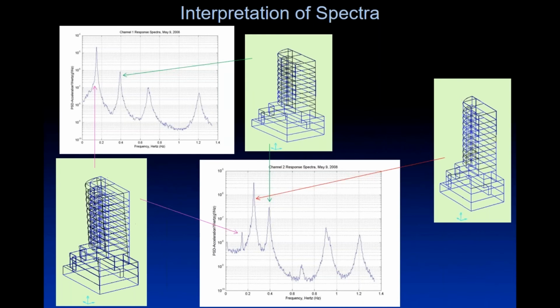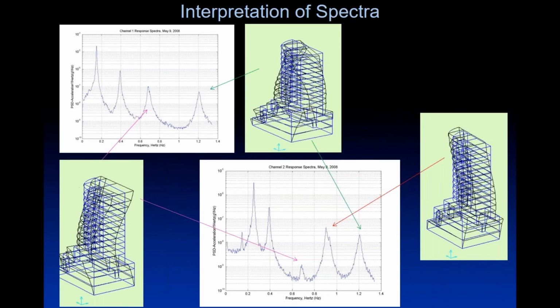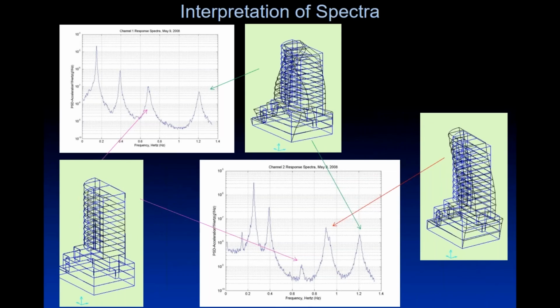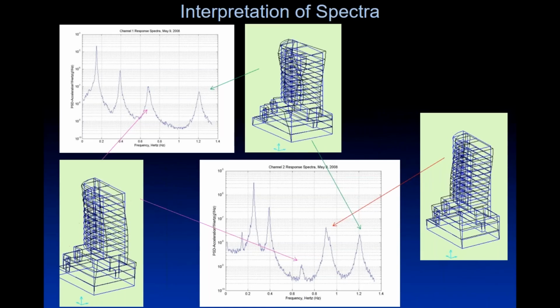There's just a little bit of twisting going on there. Look at what's happening in, let's call it the north-south mode across on the right of the screen here. Now we've got a mode of vibration measured in that direction, which is 0.25 hertz, and just a small remnant in the east-west direction there, which is just because there's not very much motion there.